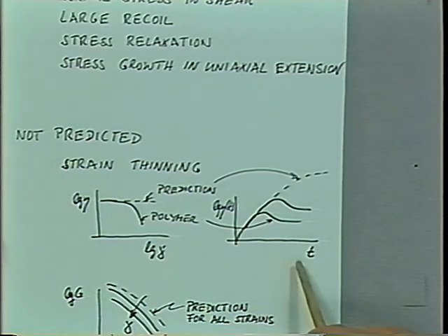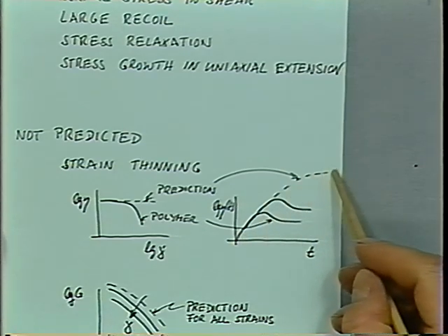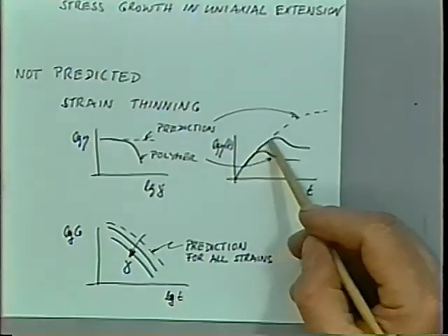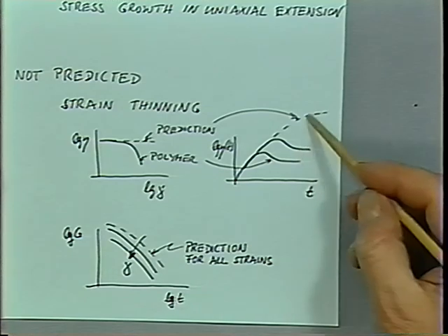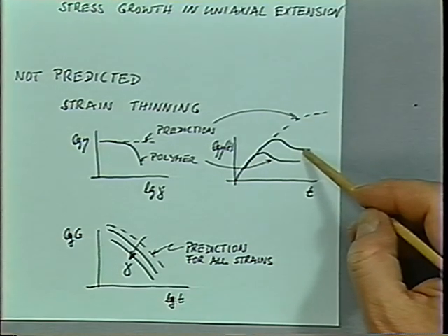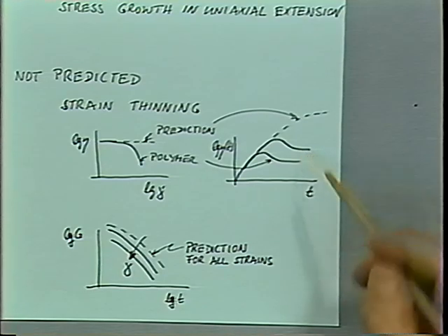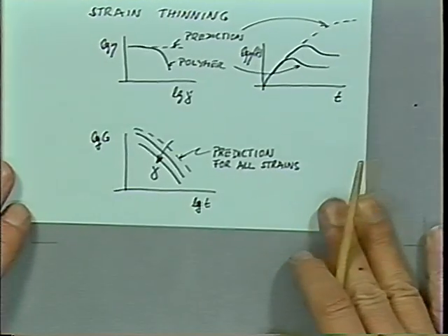Now the viscosity in a startup experiment would grow and level off at very low rates of deformation in the linear viscoelastic limit, but at higher rates it goes to a maximum and decays. So we have to somehow incorporate that shear thinning phenomenon in a future constitutive equation. You have to modify that equation to accommodate this observation.